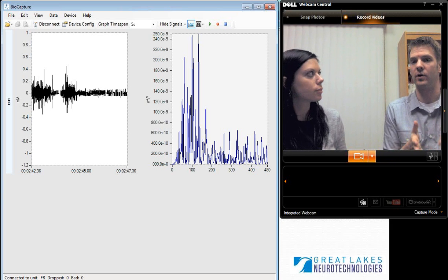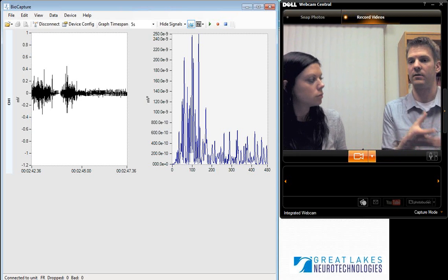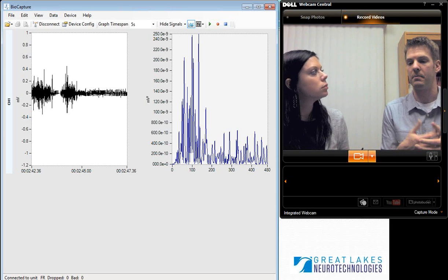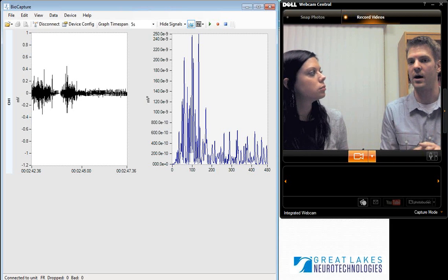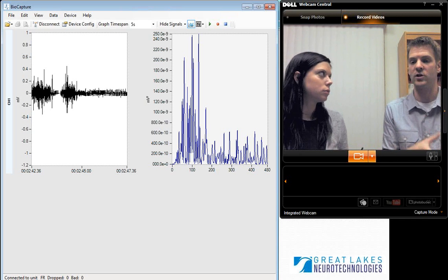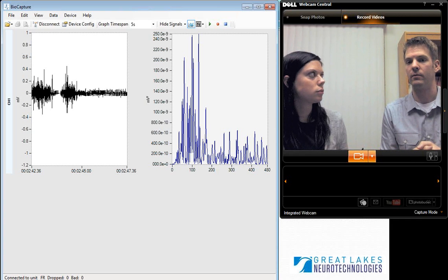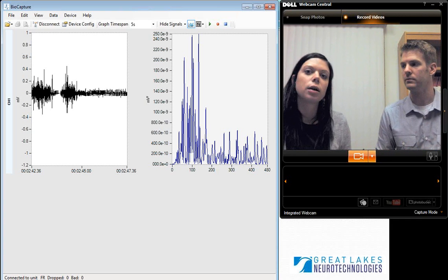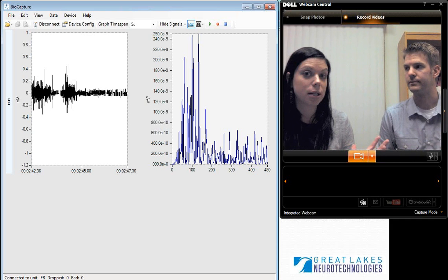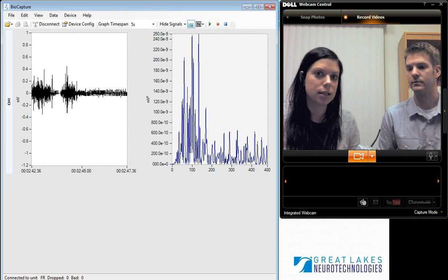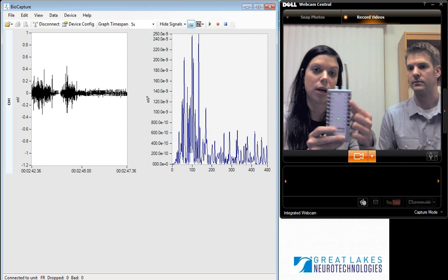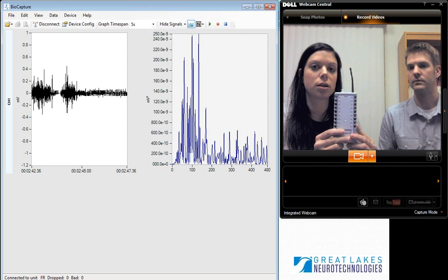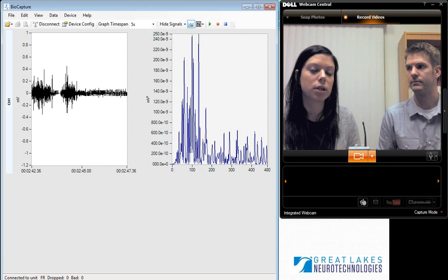Again, you want to make sure that the frequency content of that signal is low enough that it's not going to be significantly distorted by the filtering stages that happen before the analog to digital conversion. So provided you're in the right ranges and you're looking for the right frequencies, it should be no problem. The input range on the channels of the BioRadio is plus or minus 2 volts. So as long as you have an output that's within our input range and the appropriate interface to connect into the channels of the BioRadio, we have a lot of customers who integrate their own custom transducers pretty frequently.